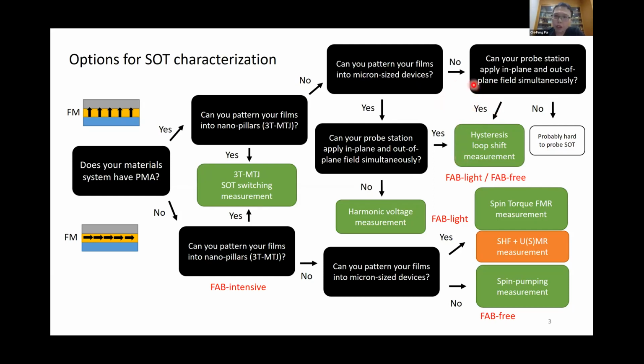And so if you can do that, you can characterize SOT efficiency. But if you cannot apply the in-plane field and out-of-plane field at the same time, but you can apply a one-direction magnetic field, you can still use the standard harmonic voltage measurements.